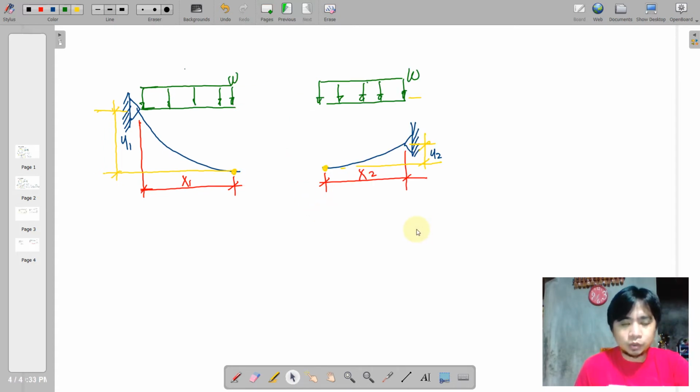Then we section the two, considering the left and the right portion. So remember, at the lowest point, your slope is 0. Therefore, the component of the cable force at the lowest point is only a horizontal H. In this support, this is a pin connection, so there will be two reactions, vertical and horizontal. Therefore, it will just have a tension that is parallel to this curve.